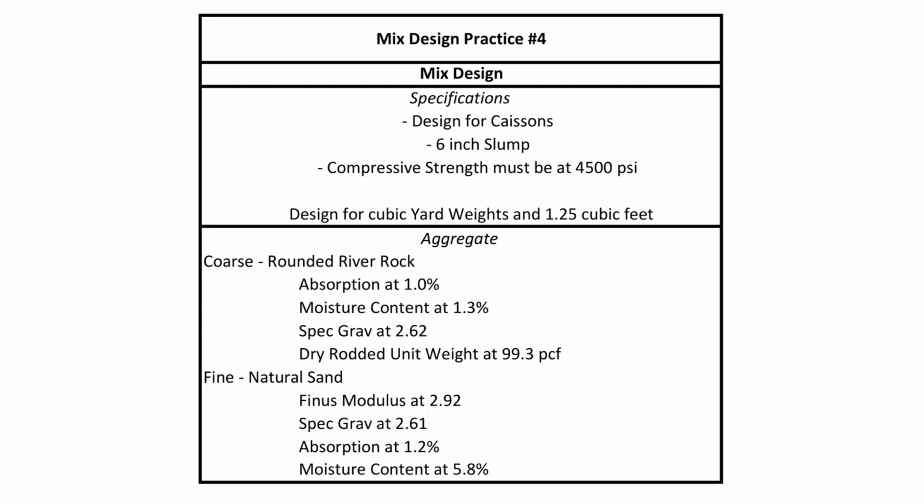Okay, fine ag, we got an FM of 2.92, specific gravity of 2.61, and we have an absorption of 1.2. It's a high absorption, and a moisture content of 5.8%.